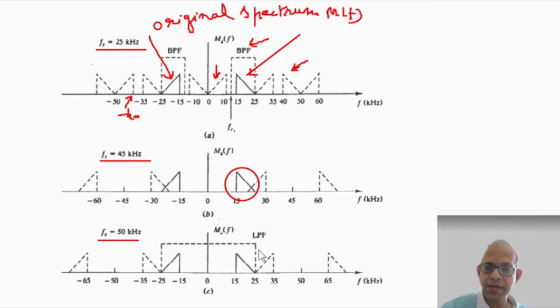and we can still recover the original signal. The point is that for a bandpass signal, it is possible to sample at a rate less than the Nyquist rate. Still we can recover the signal through suitable bandpass filtering. However, not all other frequencies higher than this frequency in this example are useful unless they exceed or equal the